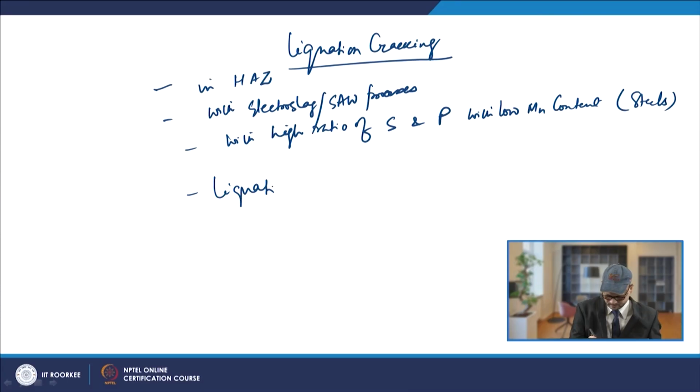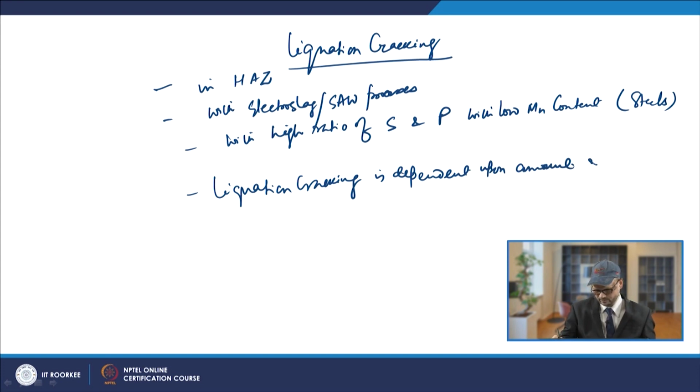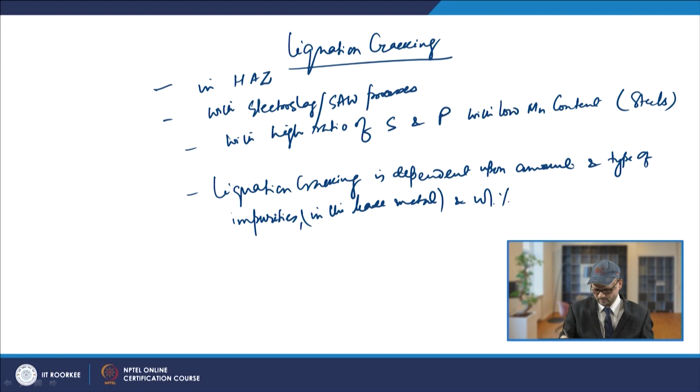So, liquefaction cracking is dependent upon the amount and type of impurities in the base metal, the volume percent and density of inclusions, and the degree of restraint.